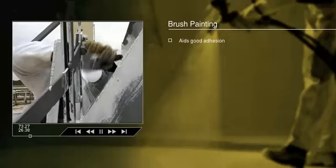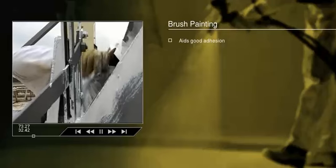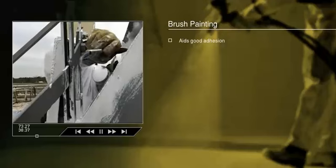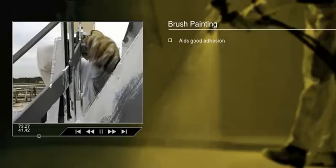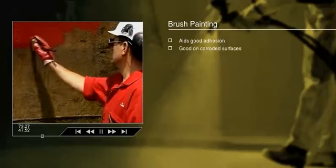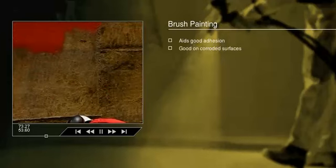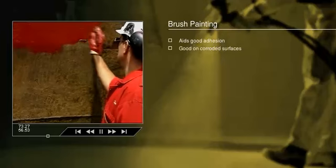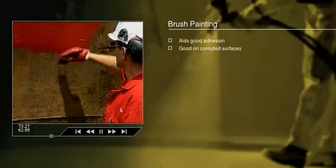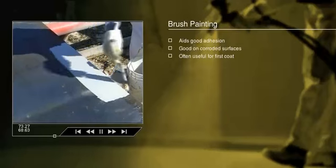Brush application can be advantageous for application of coatings on surfaces that cannot be fully and properly cleaned. The superior wetting action achieves better contact between the coating and the surface. This is especially useful on rusted steel, where spray application may leave the coating sitting on top of the corrosion layer with little or no penetration, and therefore little or no adhesion. Even when repainting old paintwork for maintenance, it may be helpful to brush apply the first coat.